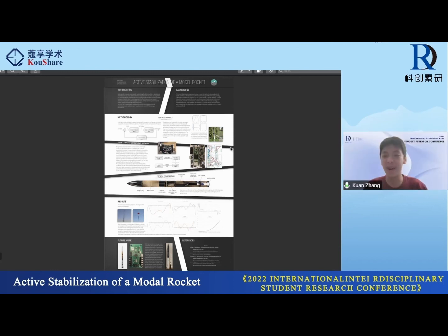Well, most model rockets are stabilized using fins. So this is a completely new system, which essentially adds computer guidance to a model rocket. It allows the model rocket to control where it's going, so it's actively controlling its course. This is much more complex than a regular rocket, which just relies on the wind to stabilize it with its fins. In this case, it's a computer running specialized software to tell itself where to go, to monitor its orientation, to correct for it, using a gimbal motor. So yes, essentially, it's a computerized rocket that's able to guide itself.